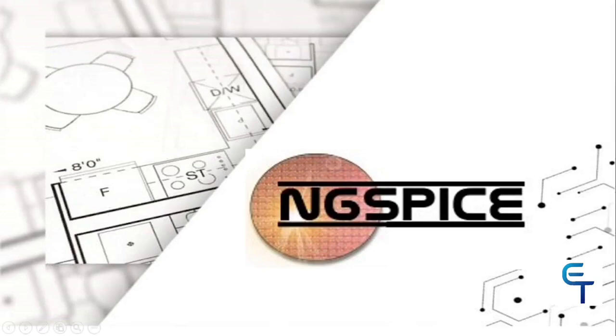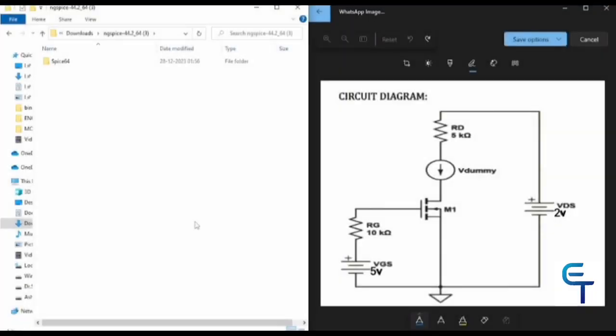In this video, we'll be learning how to plot the characteristics of an Nmos transistor using Ngspice. In our previous video, we covered the basics of Ngspice and also walked through the download process. If you haven't watched that yet, be sure to check it out first. So in today's video, we'll write a simple Nmos circuit using a netlist, simulate it in Ngspice, and finally plot IV characteristics, which basically shows how the current through the Nmos changes with different voltages.